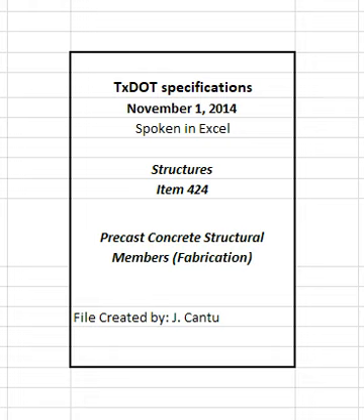4.2 Fabrication. Prepare a casting schedule on department-approved forms per DMS 7300, precast concrete fabrication plants, and submit it daily to the department before fabrication. This requirement does not apply to project-specific minor prestressed member or project-specific non-stressed member fabrication plants. Perform fabrication during daylight hours unless the production site has an approved lighting system. Submit lighting details electronically to the engineer for review before installing lighting system. Allow for plant and department inspection in accordance with Item 6, Control of Materials.